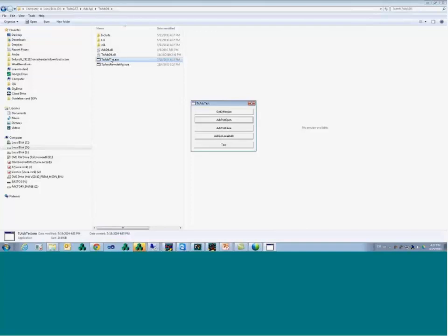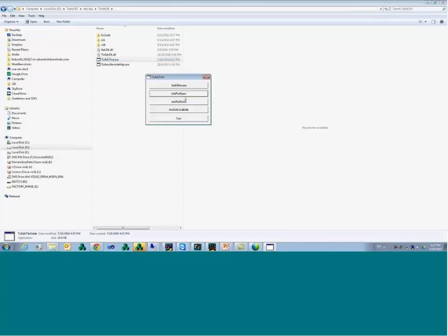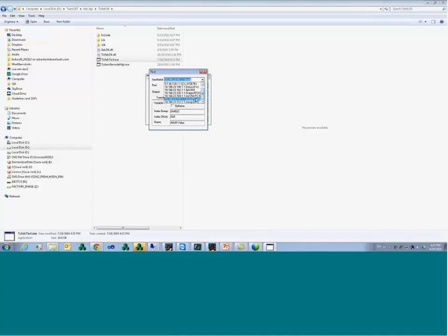You can try to troubleshoot on the problem that you're having on the network between your computer and the TwinCAT runtime. So first thing you do, you click on ADS port open, you got a confirmation, and you go to the test button. So here you're going to see the list of all the registered routing, so all the runtime that you can talk to. So I'm going to put here, for instance, the one that you're talking to is the 164. Okay, the port number is 851, and I'm going to talk by variable name.